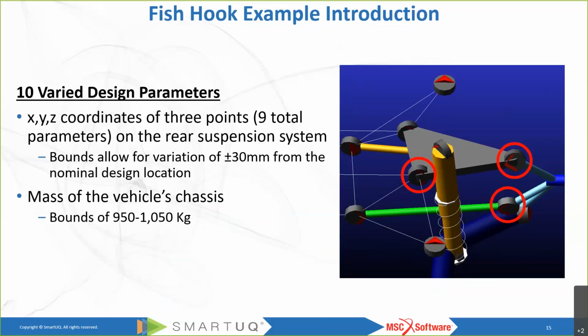So these are the 10 factors that SmartUQ is ultimately going to ask Adams Car for. We're going to build the DOE across these parameters, and then we're going to ask Adams Car to run these simulations for us.